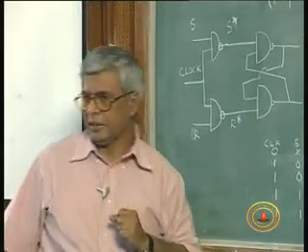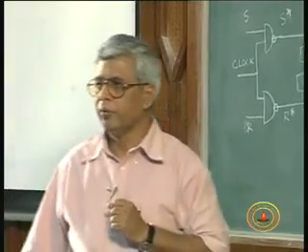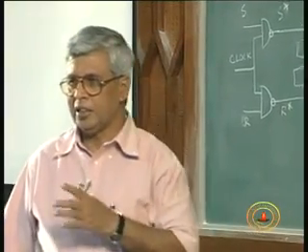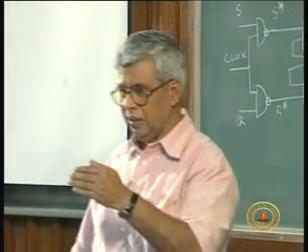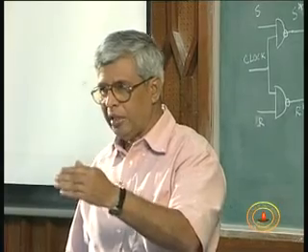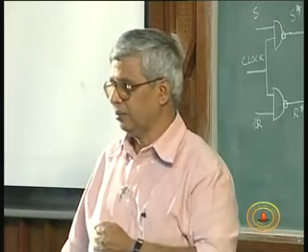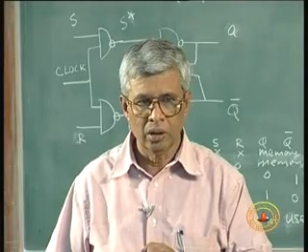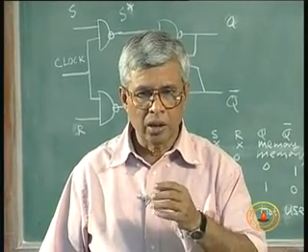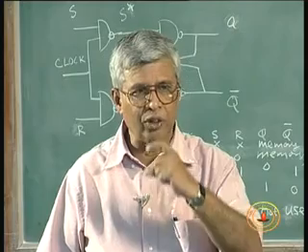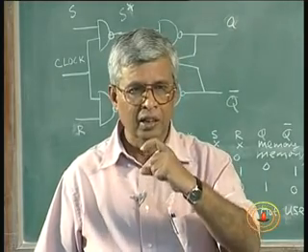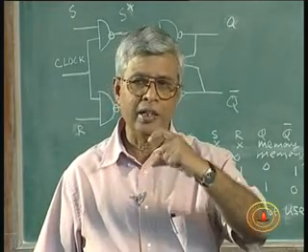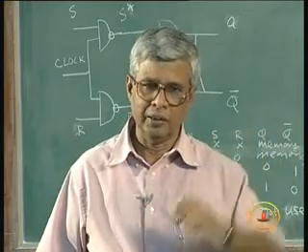Why do we need this clocking operation? As I said first, this may be the output of a latch, which may be the input to the next, subsequent circuit, and any frequent change, sometimes unintentional, will go through as a chain reaction to the next state.